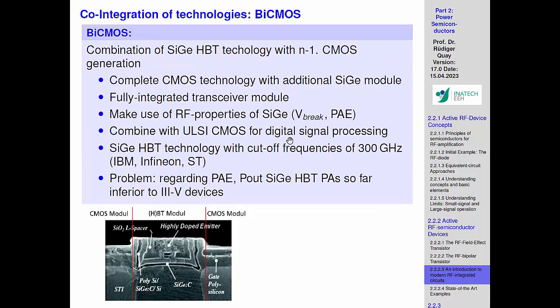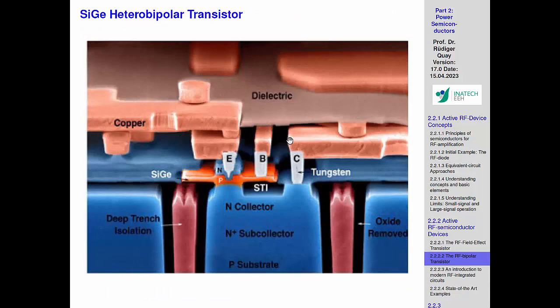And where do you see this here in this plot? That the RBB is low, so they are also taking some copper, and then it will broaden here at the back. You cannot really make this much wider here, because then you would again build capacitors, but we want this wide. And it's a detailed optimization. So here you can see really the 3D contradiction. Ideally the base contact would be wide to reduce the resistance, but at the same time you have to keep the junction capacitance to this side low. So there's a compromise.